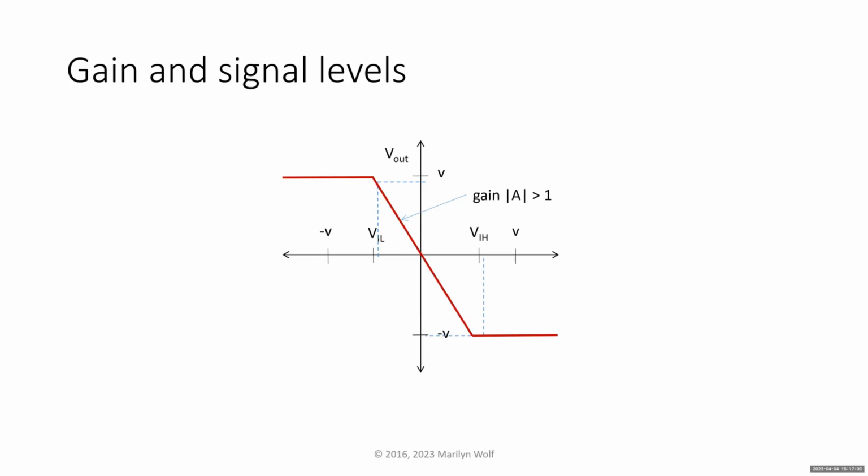If we were building an audio amplifier, we would want gain in the 10 to 100 range, for example. Clearly, if we're designing a logic gate, we would like that gain to be at least bigger than 1. If it's less than 1, that means we put in a voltage that we think is solid on the input side, and it's going to give us potentially a not so solid logic level on the output side. Now let's look at a lower slope.